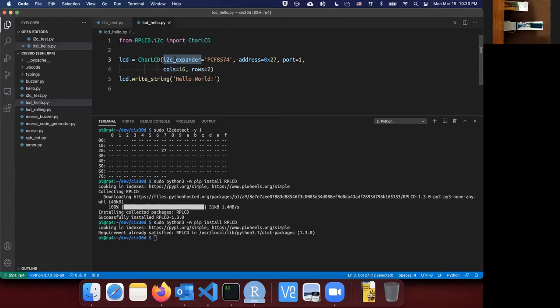What's a port expander? Port expander really is the fact that the LCD exposes the backpack. If you look at the I2C backpack, it has 4 ports coming out, and in fact, the LCD has 16 ports. There's a port expansion going on here for this to be connected. So there's a chip that controls the port expansion here.